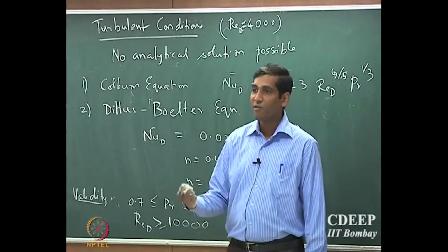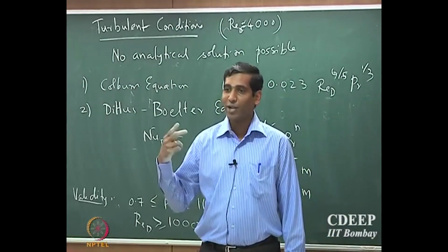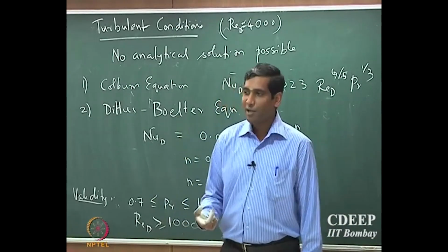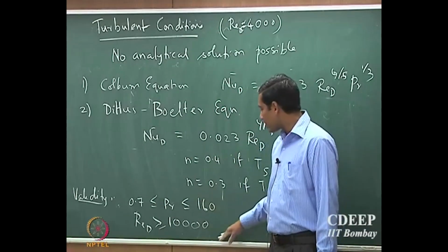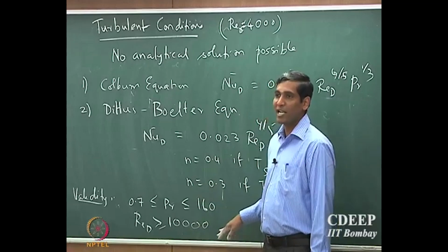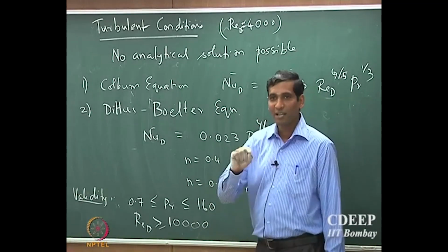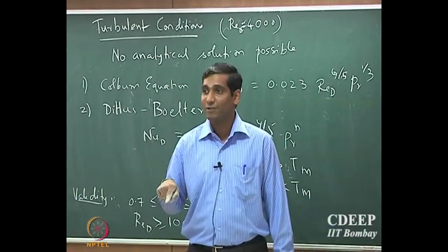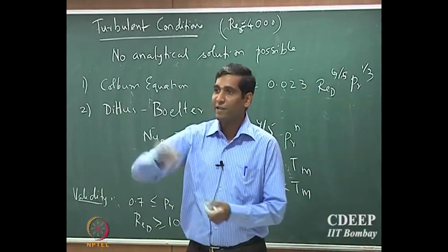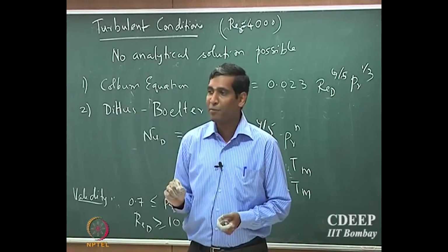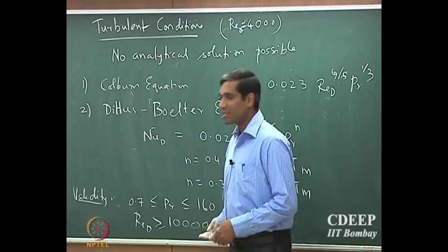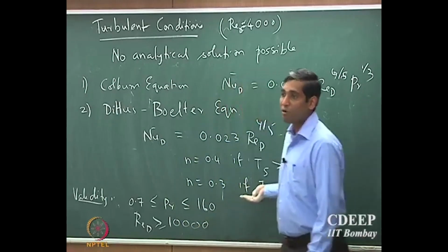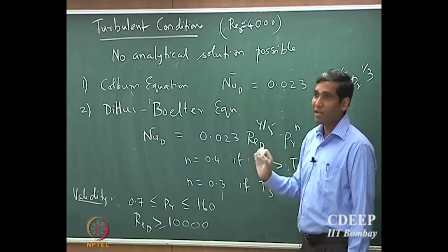So, some of you who have actually done this experiment and have not calculated the Reynolds number, which you should have, if you have not calculated and checked whether the Reynolds number is greater than 10,000, you will see that there will be a variation in your prediction. The straight line fit that you are trying to fit your experimental data will really not fit your experimental data very well unless your Reynolds number is sufficiently large where the correlation is valid. Okay. So, that is very important.